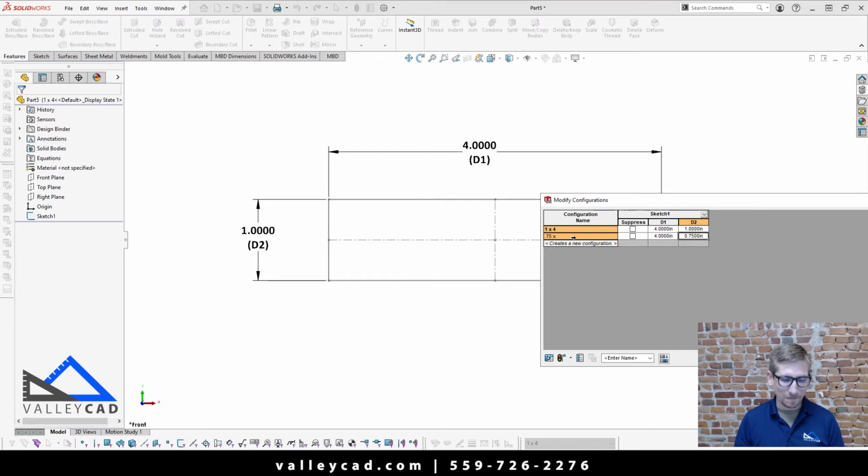See what I'm doing there? Now I can push tab again or come down here and click on this next cell. Oh, looks like I forgot that 4, shoot. Well, if I slow click on it, you'll notice that I can't go into edit name mode. So to let you know, when you're here, you simply right click on it and you say rename configuration. That'll bring up your new name convention mode. Say okay to that, updates the name. Not a problem. Now you simply come in here, I'll make this next one so it's a 0.5 by 4.